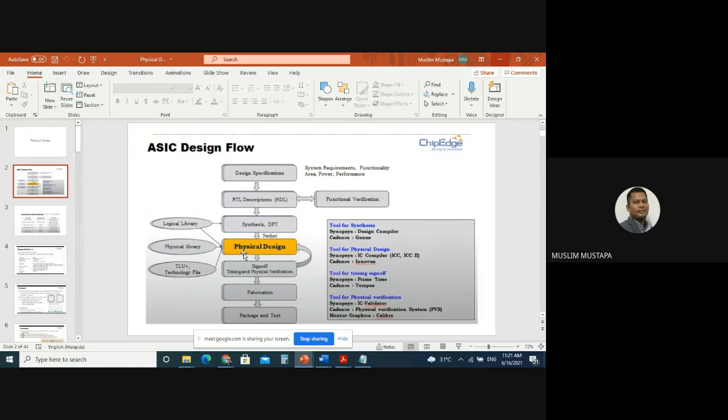So as you can see, this is an ASIC design flow, which is similar to the SoC design. The only new thing that needs to be involved in the SoC design flow is the analog circuit, for example, micro electromechanical circuits, where you want to embed the sensor together with the SoC, or any analog circuit that you want to embed together.